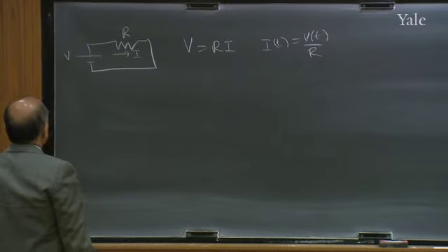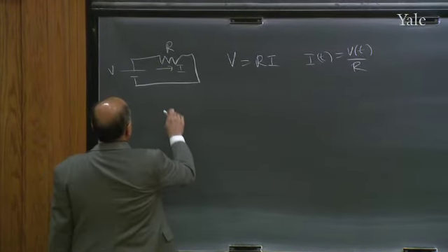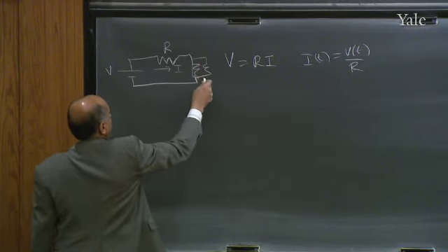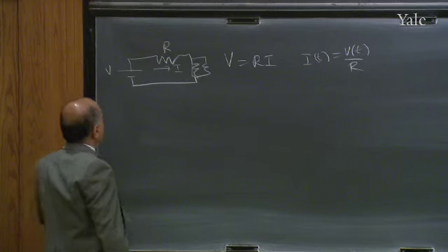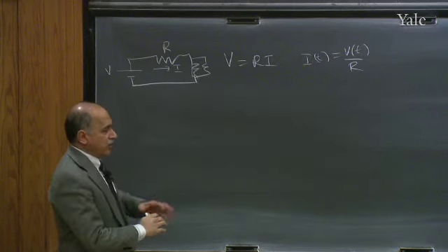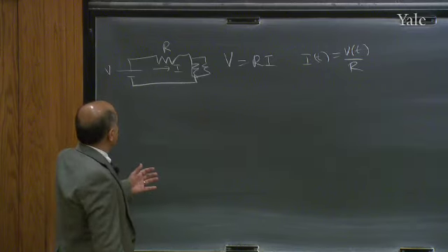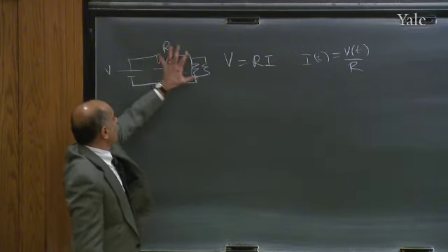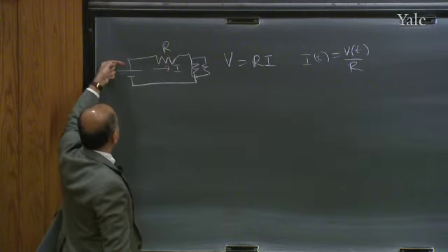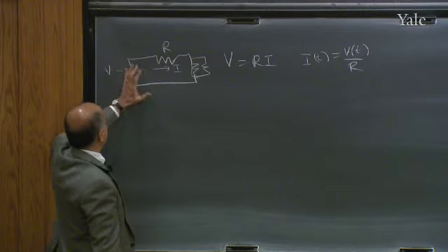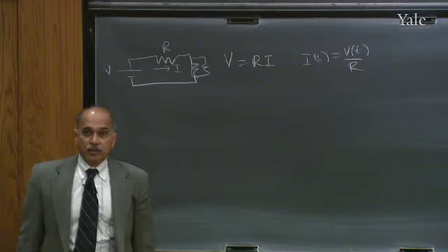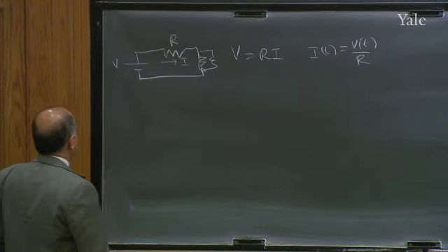And you can make the network more complicated, put a few more resistors here, a few more there, resistors within resistors. Doesn't matter, because we can always, in the end, combine the ones in series, then lump them with the stuff in parallel, till the whole thing to the right of this is one single effective resistor. Then you find the current coming out of the source as V divided by that guy. Then every time it comes to a branch, we sort of know how to divide it. So resistor circuits are very easy.